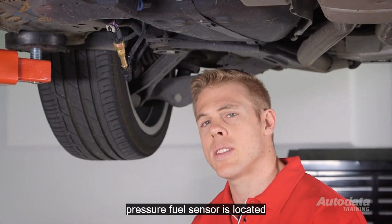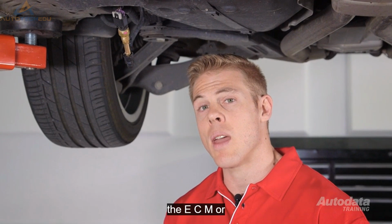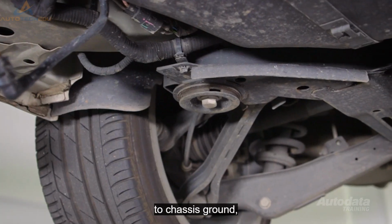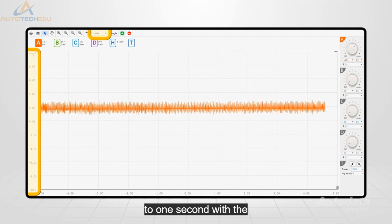The low pressure fuel sensor is located just after the fuel pump. It communicates with either the ECM or the fuel pump control module. Backprobe the sample lead at the signal circuit and the other to chassis ground. Adjust the Y-axis to 10 volts and the X to 1 second.